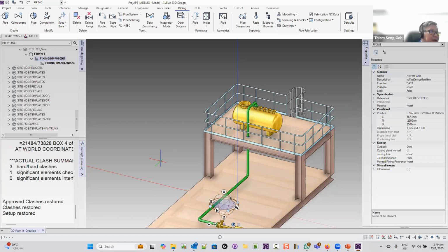Is it possible to detect clashes with bolts, nuts, support sockets? It is possible, but you must model the actual item, whether it's a cylinder, etc., in your catalog. When you model it in the catalog, you can make it not show in your detail view, but it will still check for clashes. Because these are hard items, we suggest that you use a hard method so that you come out with a hard clash rather than a soft clash. So that is possible.